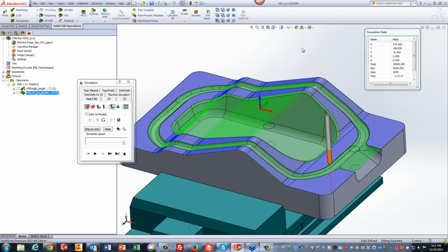Now, however, there is one thing I don't really like too much about this toolpath. If I take a look at the toolpath itself, you'll see that it's going from this end to over this end directly, no problem with that. But the feed that it's actually using is a relatively slower feed than it would be. It's not using the actual maximum feed of the part.